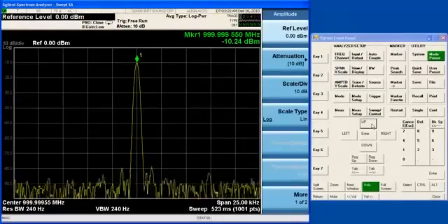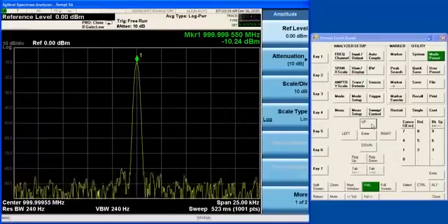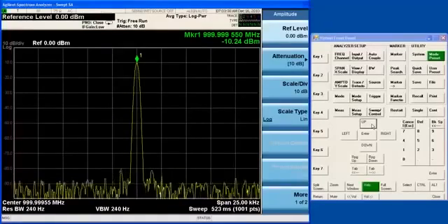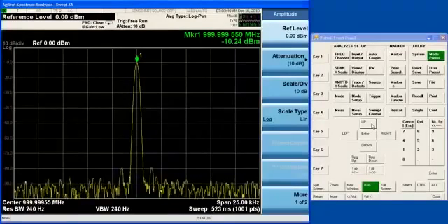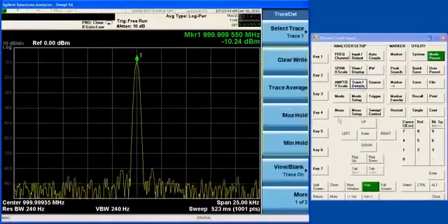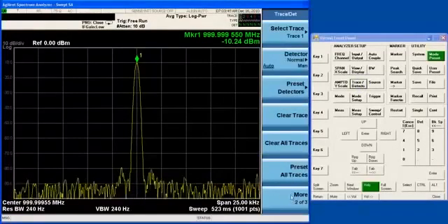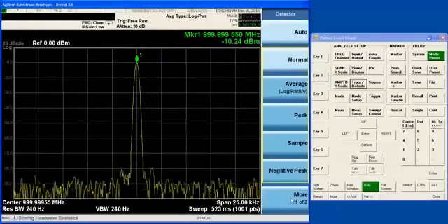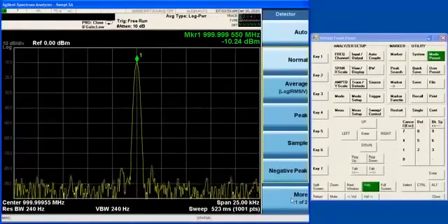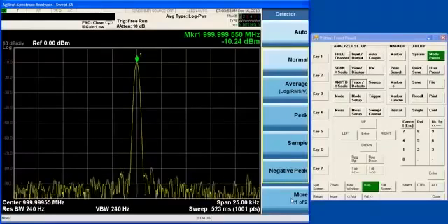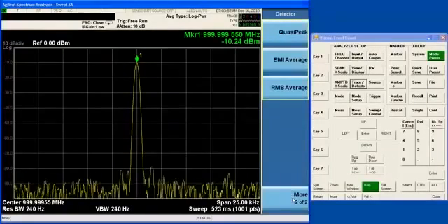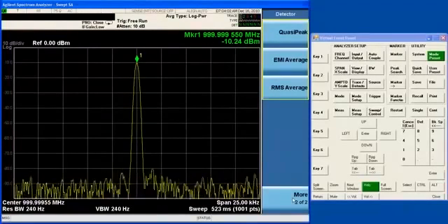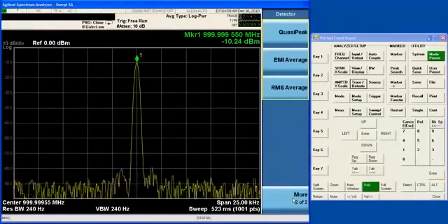an analog log amp. Another advantage of the digital IF is that you can use a single signal path to make all your measurements, even with the EMI detectors, whereas with analyzers that have an analog log amp, you have to use a different signal path to make normal detector measurements as opposed to EMI detector measurements. So the accuracy of the X series for EMI measurements is unsurpassed.